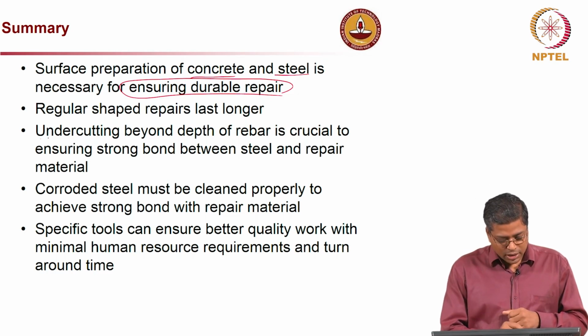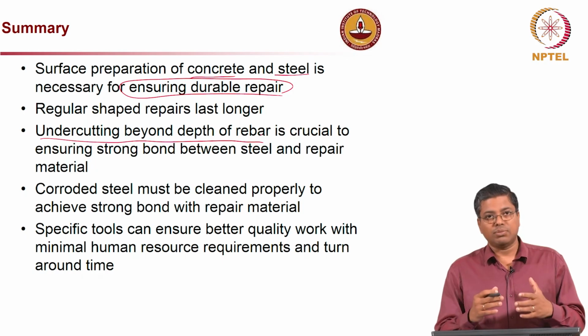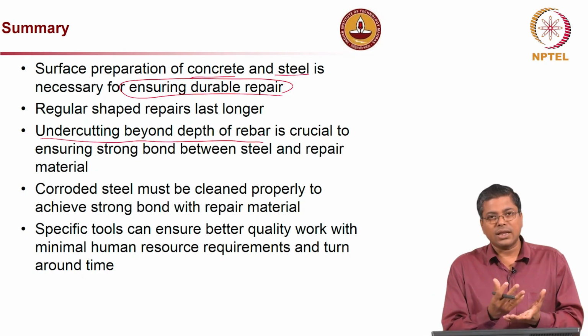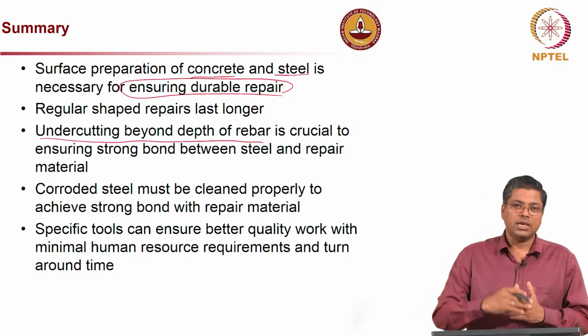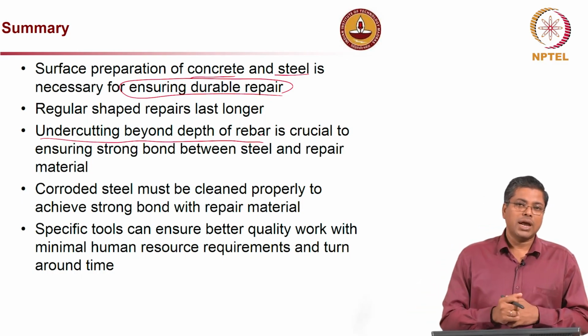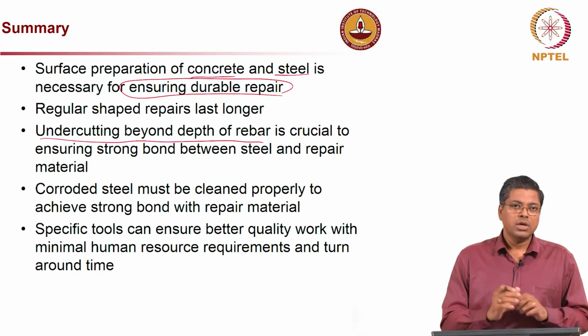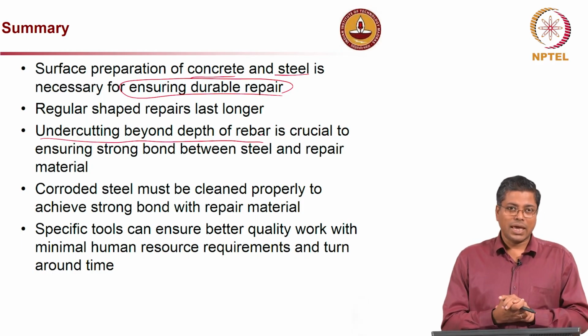And undercutting beyond the depth means the entire rebar surface should be exposed, even the surface which you cannot see behind the rebar; that concrete also should be removed, so that you get better mechanical grip.